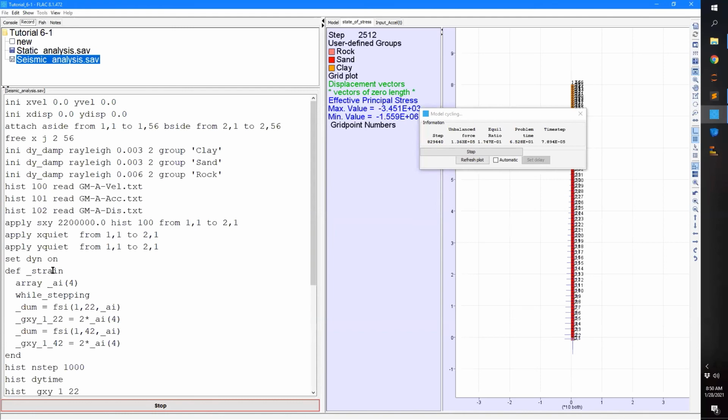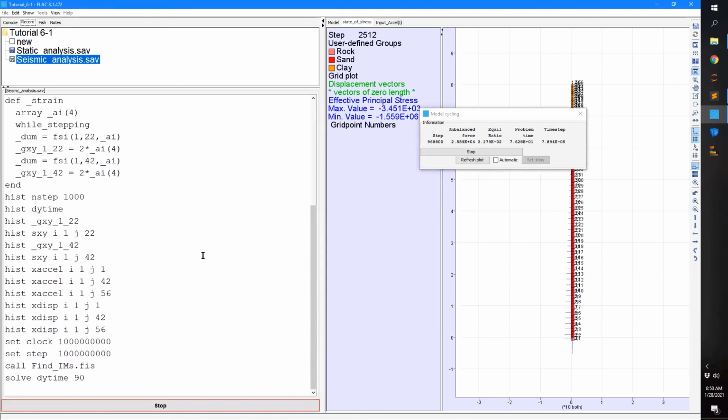So in that, it's unable to accurately model the changes in excess pore pressure, the associated settlements and aspects like that, where a constitutive model such as NorSand, PM4Sand would likely do a much more accurate job in doing that. So we're still waiting for that to complete.